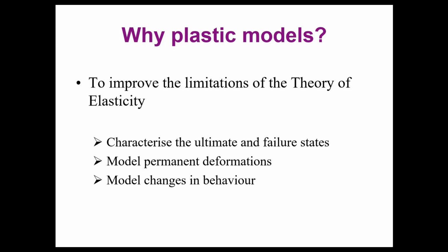The soil is not able to recover a lot of deformation when you release the loads, so you are going to recover just a little, and the most important deformation will be all plastic. So we need a plastic theory to capture the plastic deformation, and the isotropic linear elastic theory does not allow us to capture these permanent deformations.